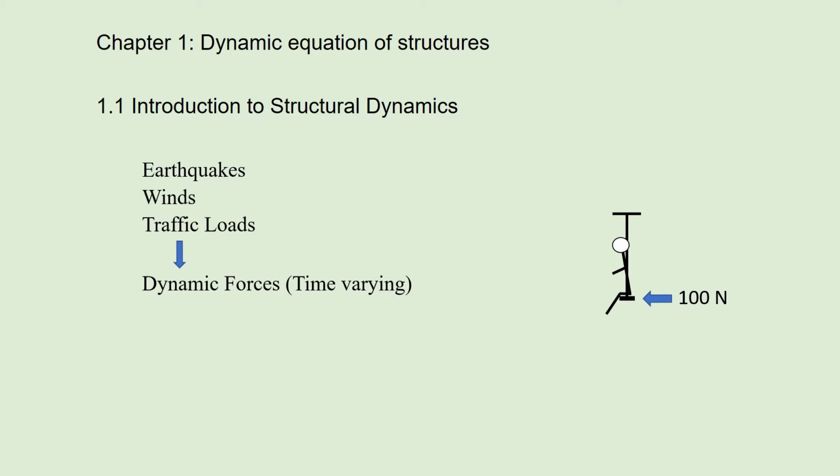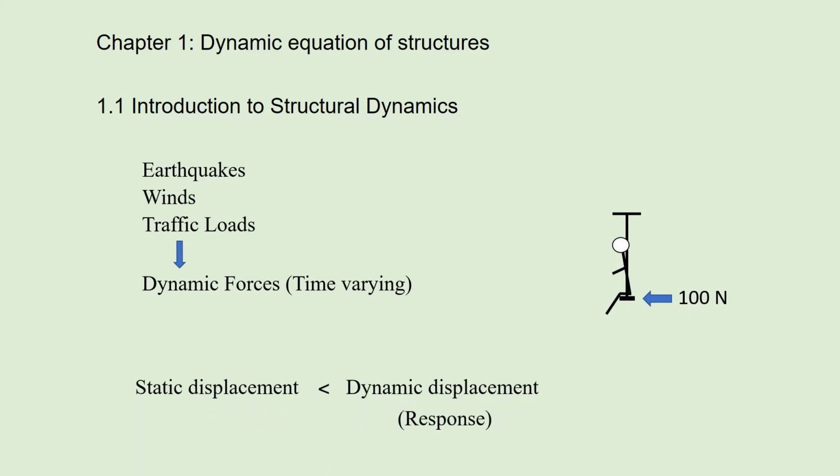The swing is getting larger and larger, let's say 20 centimeters, 50 centimeters, even 1 meter. It means the dynamic displacement, called response, can be larger than the static displacement, which creates a dynamic problem. Now you understand why we have to study structural dynamics.